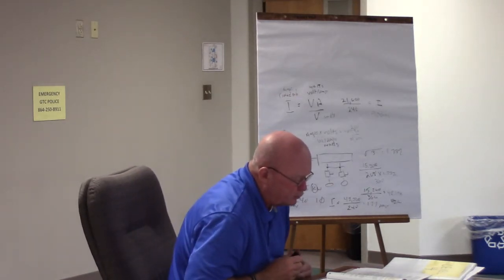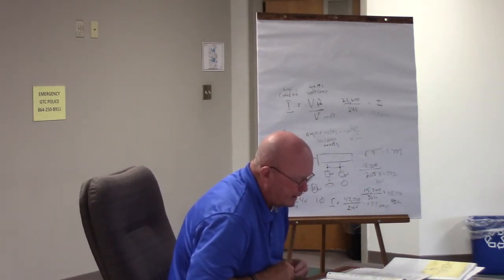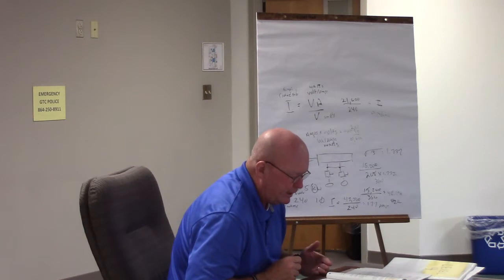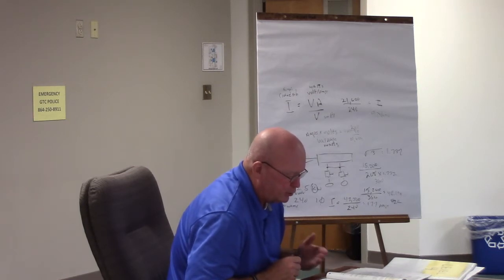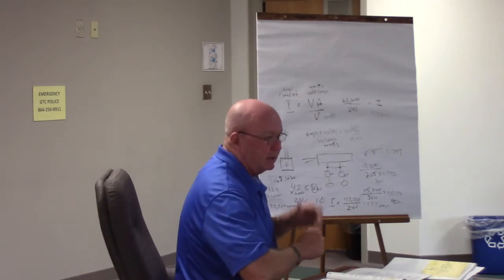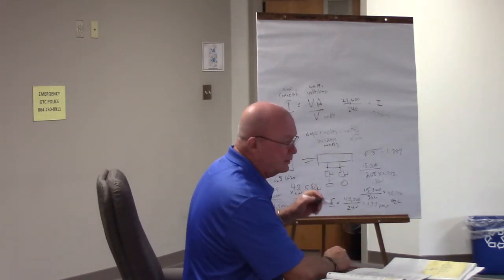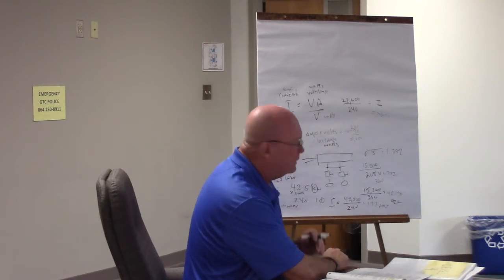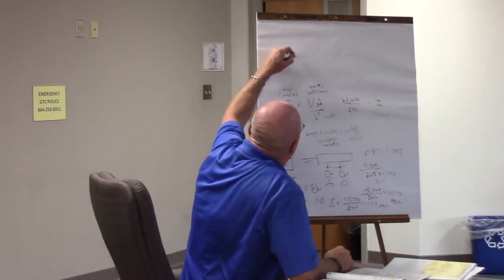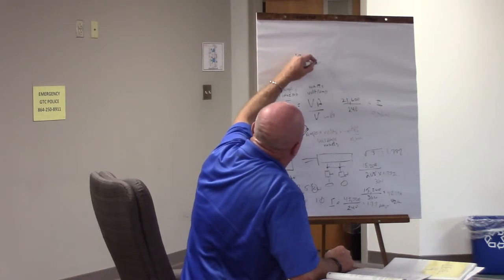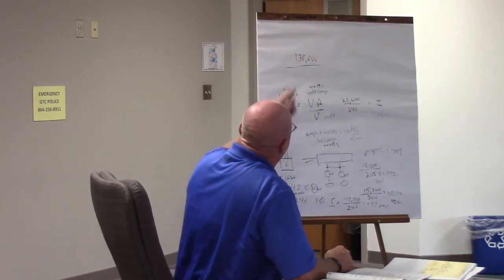Example number 2, what's the ampacity of a three-phase panel with a calculated load, 135 kVA, same thing, 208. We got to do 2 steps. First thing we got to do? We got to take that 135 and change it into what? 135,000. Right. That becomes our watts or our VA.